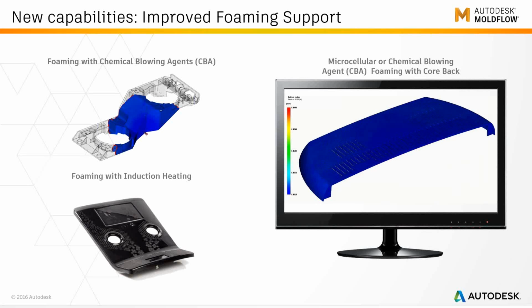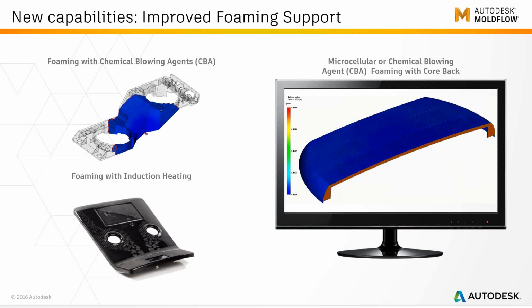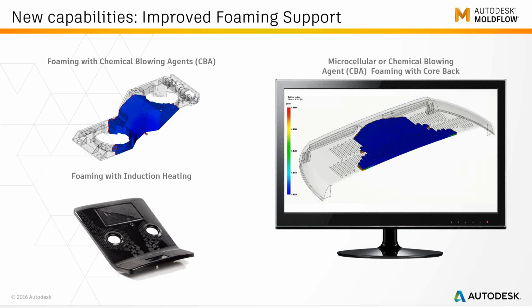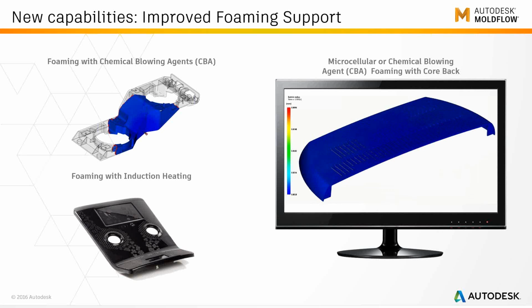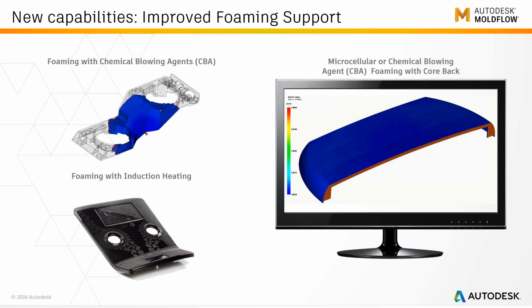As most of you know, in MuCell or blowing agent capabilities, the bubble size and bubble density is very much driven by the pressure drop that occurs during packing. The way you can massively improve the structure of the foam is by moving the core back.